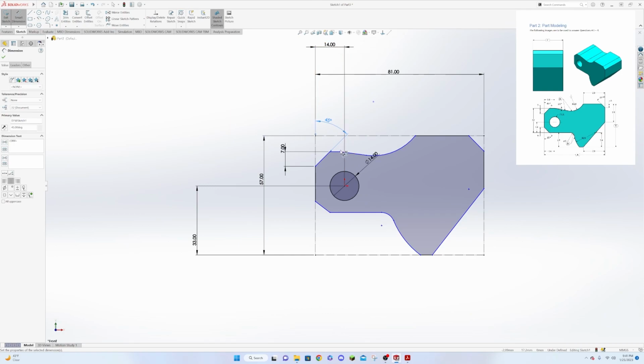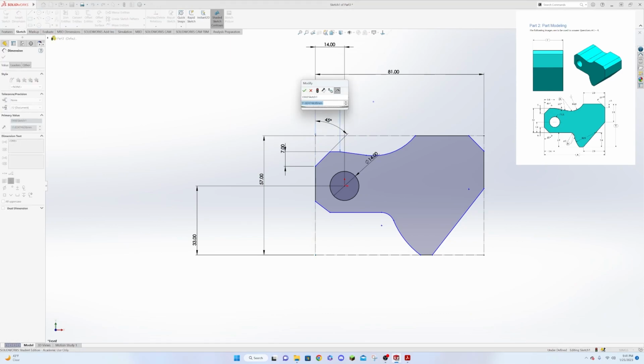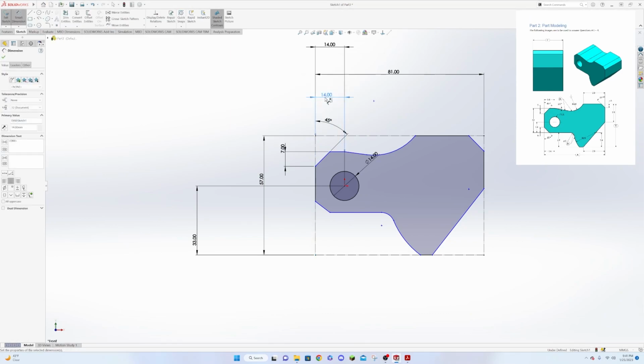And we know that from this point here to this line, our length is 14. So that shifts that over a little bit. All right. We know that this angle is 10 degrees off of this horizontal, but without putting a reference line in here, we know that this is 180. It'd be 180 here. So if we know that we're 10 degrees off of that, we can say that our angle here to here is 170.